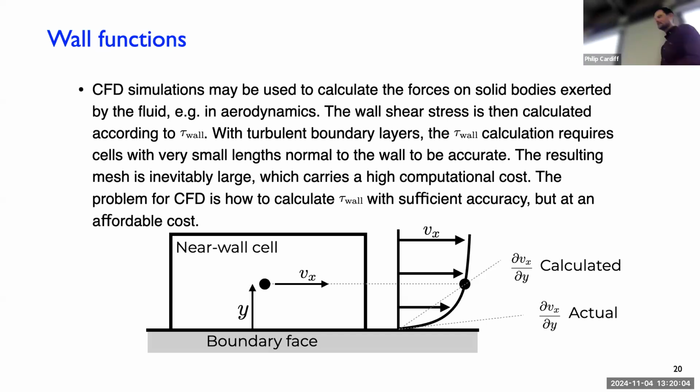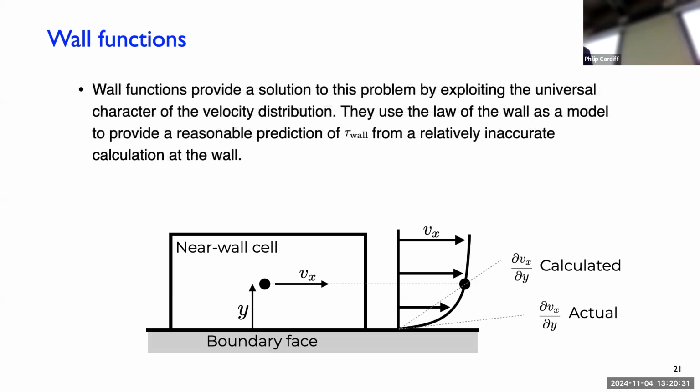Okay. So in a laminar flow, it might not be that hard to get it in this region, because this region is bigger. But for a turbulent flow, this laminar sub-layer can be very, very thin. So you might need the thickness of the first cell away from the wall to be very small. So this is a challenge, and this law of the wall is something that can help.